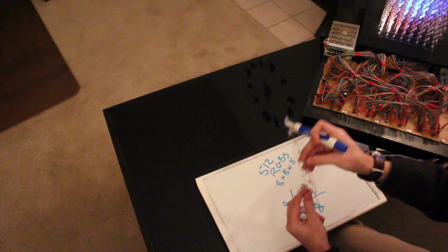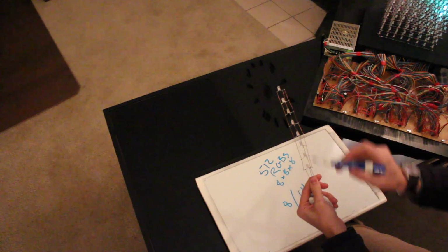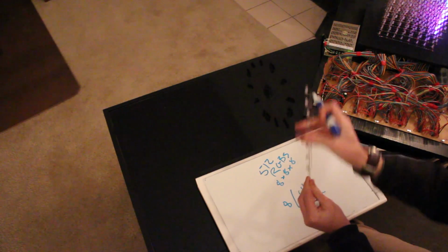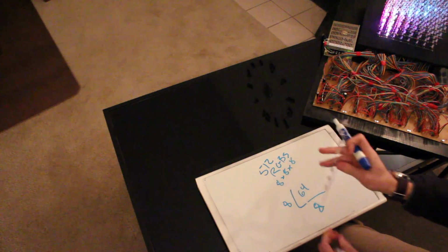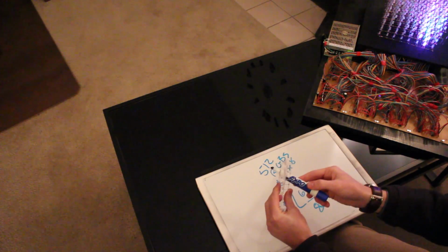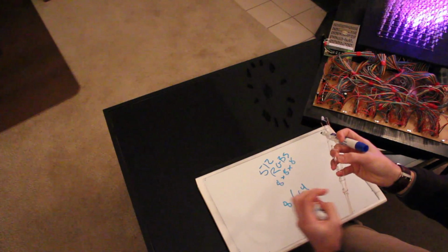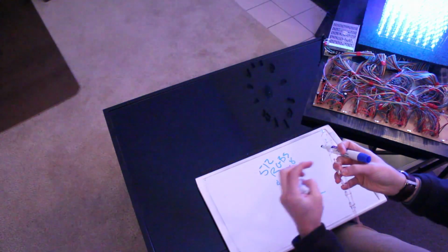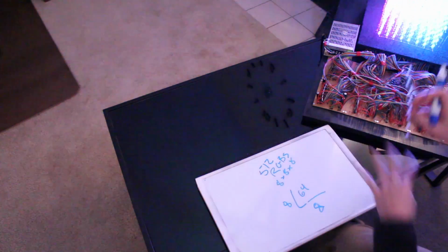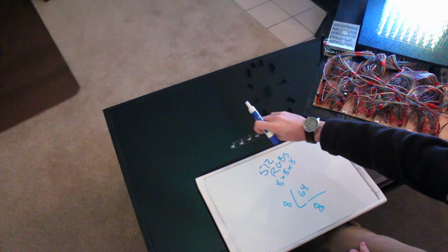What we have here, you'll notice there's 3 leads at the bottom. That means we have the R, the G, and the B all connected per pillar. The anodes are connected per each level. You can't see that lead, but those were all sticking out here. The anodes of all the levels, and there are 8 levels, are tied together.